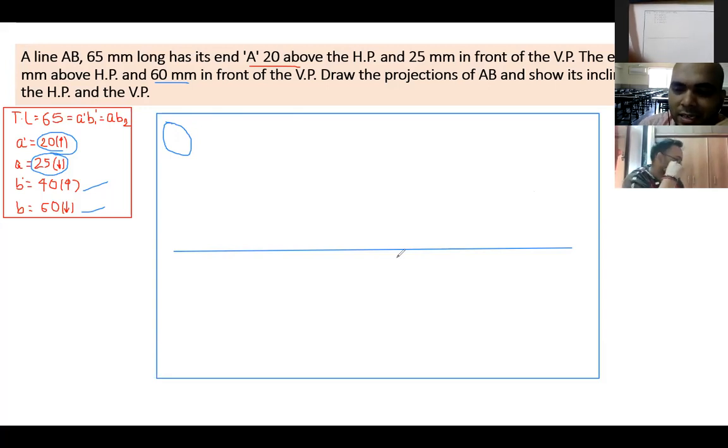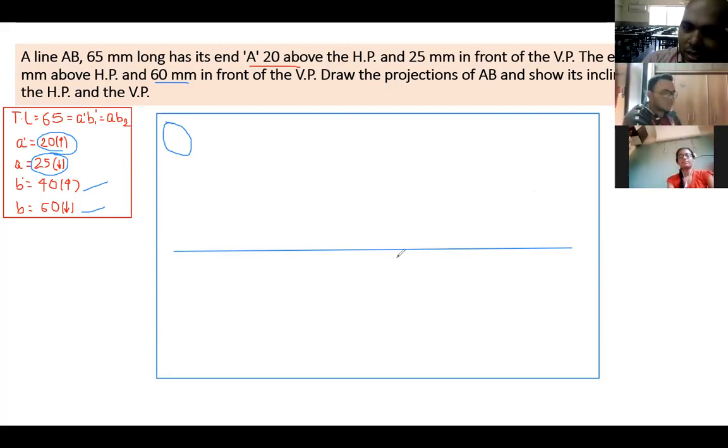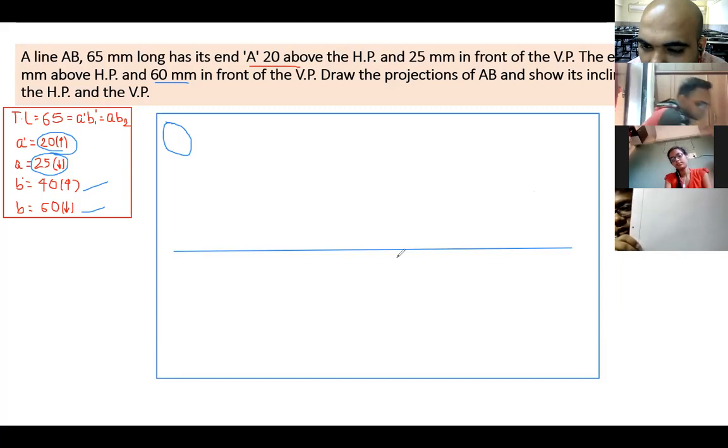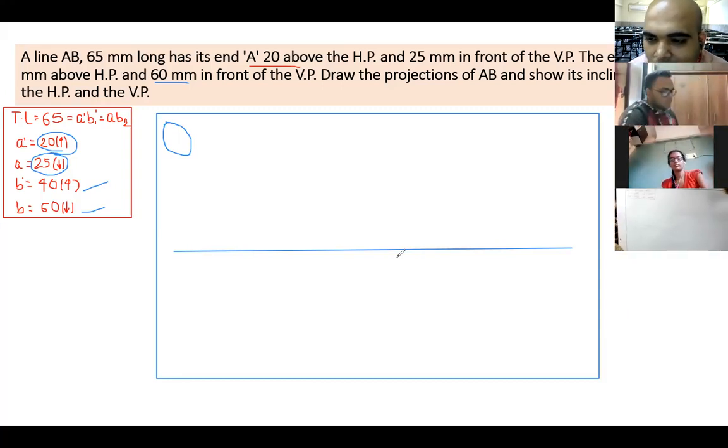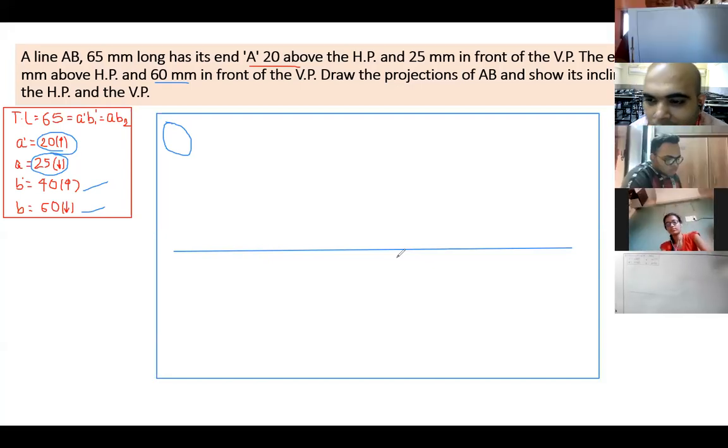You all are making the line dark. I'll tell you which line you have to make dark and which line light. So every line, everything, make it light. I'll tell you at the last which lines you have to make dark. And I hope everyone is using H or 2H lead. No one should use HB lead, because in some drawings I am seeing HB lead used. If anyone is using it, it is difficult for them to get accepted.